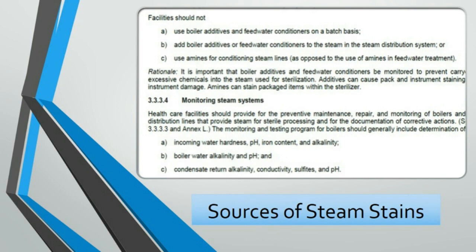And then you're monitoring the steam system as well. Healthcare facilities should provide for the preventative maintenance, repair, and monitoring of boiler and distribution lines that provide steam for sterile processing, and document corrective actions. So they're saying you need to be watching it, and not only watching it, but recording what you did when you found something out of whack.